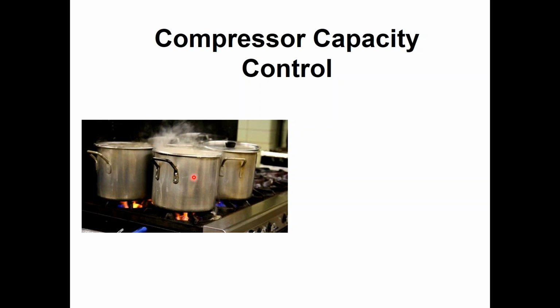My feelings on compressor capacity control are the same way. If I don't need full capacity, why would I run full capacity? I need a way to throttle it back. And VAV systems are all about throttling things back. That's literally what the dampers are doing. They're cutting back capacity. I need to have the fan, which we just took care of, and the compression do the same thing. There's no reason to run all the compression and then have only 1/3 of it be able to be used by the space. It wouldn't make any sense.